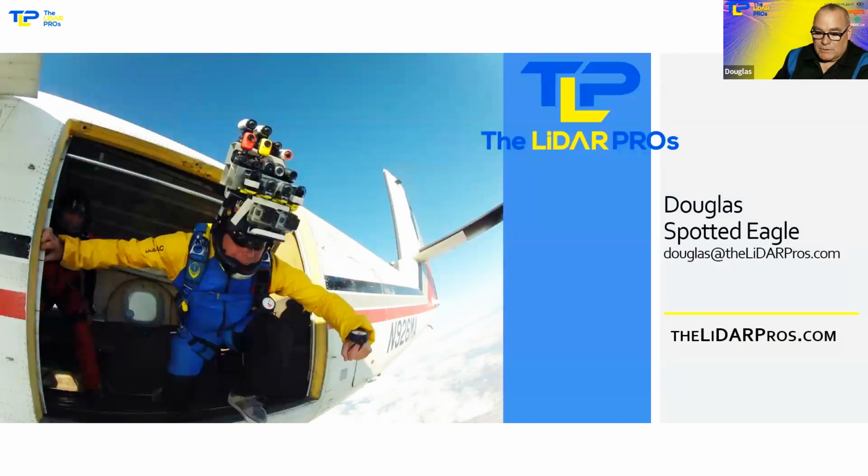Unless we've got some questions that are out there, I have not seen any questions come through on my chat. Oh, here's a couple of questions from Facebook. Can you use any type of drone for photogrammetry? As long as the camera system, or I should say the drone system, is capable of automated flight, you'll be suitable for photogrammetry. Basically, what happens is the camera records latitude, longitude, and altitude data in the metadata on the camera.